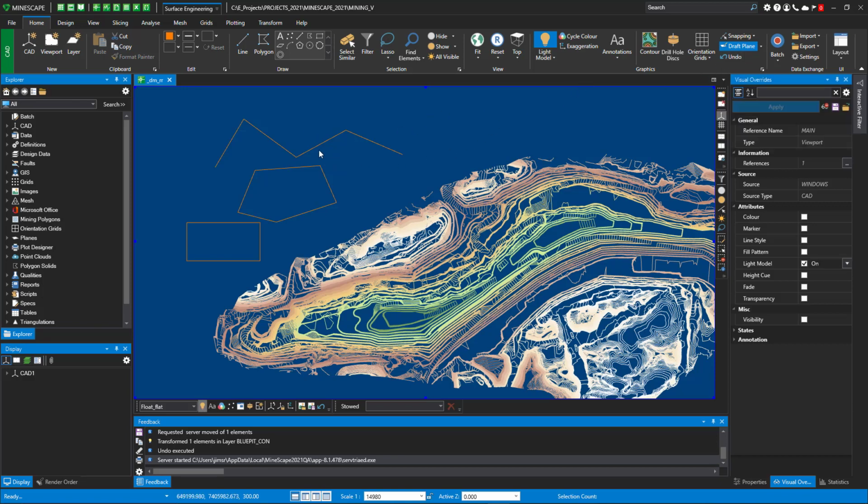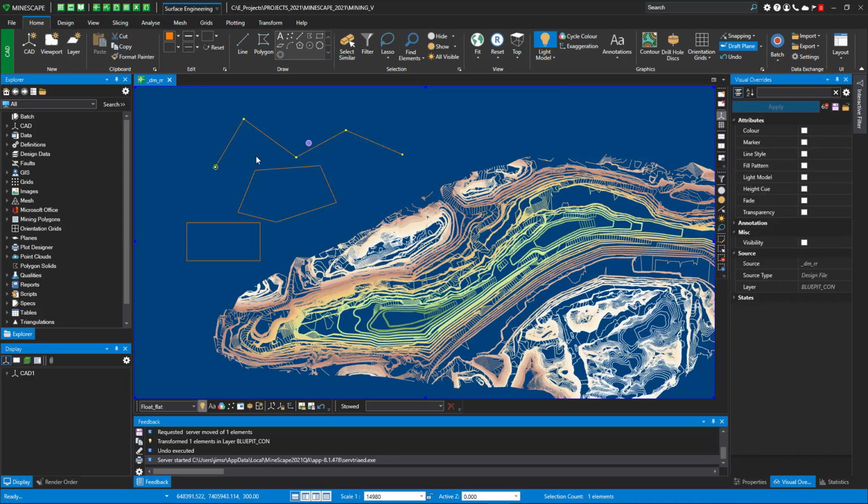and also up in the ribbon, you can select undo. If I want to insert vertices, if you notice, if I sticky snap to the element or the vertex, there's a pull down. If I hit the space bar, or I could just click on the drop down icon, I can insert vertices, and it gives you the direction of where you want to insert the vertices. If you want to insert a vertex at the midpoint, no problem. Insert a vertex at the midpoint. It's a done deal. If I want to move that, left mouse button, move it around, off you go.